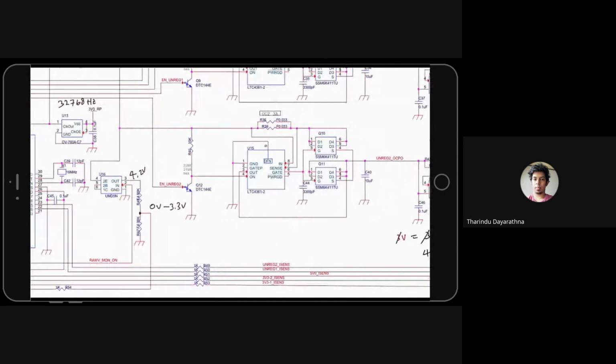One more thing. I hope you guys know this one, but I'll tell. Let's say if the PIC detect voltage here is 1.9 volt, which means the raw voltage line is 3.8 volt, because half of the voltage from here will appear here. So any question?